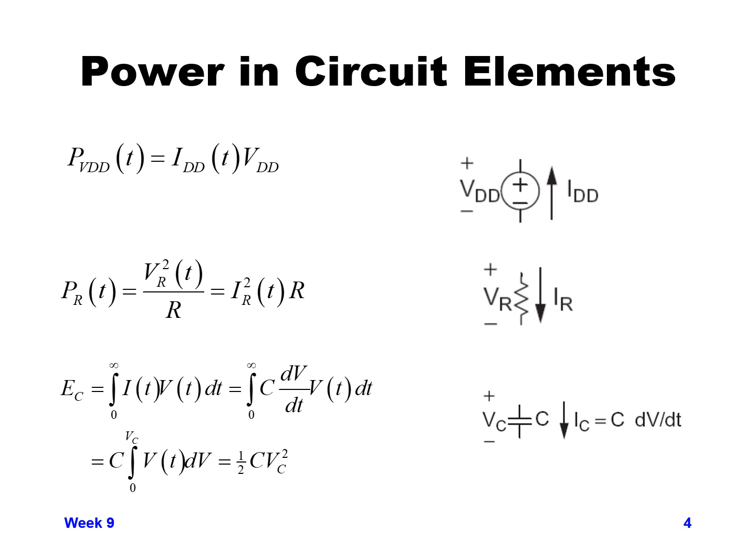Next, for a resistor, the power consumption as a function of time is V squared over R. If we go back to our basic circuits courses, it's either the voltage value across that resistance, V squared, divided by the resistance, or it can also be written as the current going through the resistor, I squared as a function of time, times that resistance value. So depending on whether you know the current or the voltage, you can get your power either way.